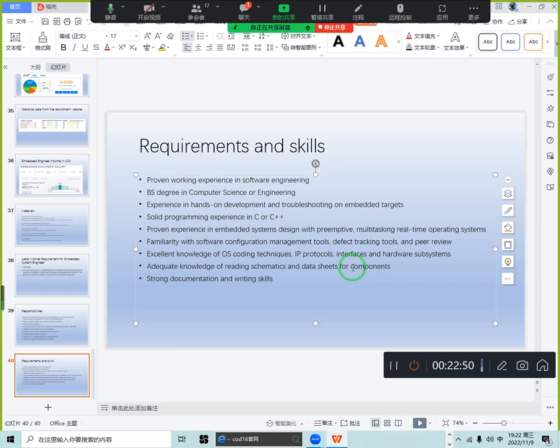Before I select a component, I will read the data sheet and find out if this component can fit my design. If yes, I will select this kind of component. However, I also will check if this component is sold on the market. If no one sells this component or the component was produced several years before, you cannot select this kind of component.